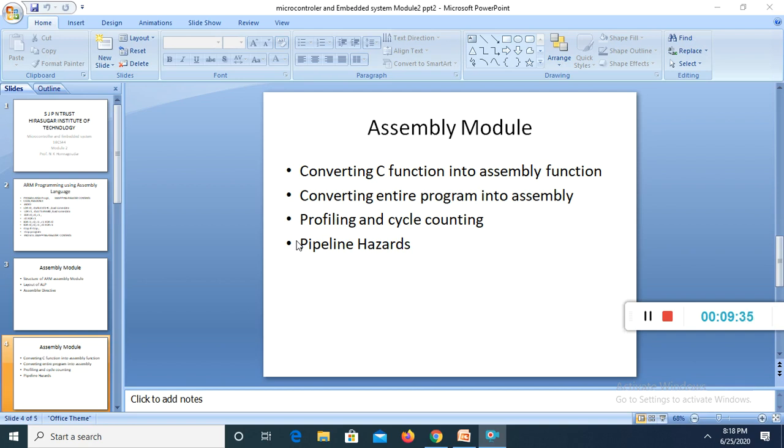It is important to note that the ARM assembler treats non-indented text as label definitions. So the return value is returned in register 0. The END directive marks the end of the assembly file. Comments follow a semicolon. We can build the above example by executing these processes.